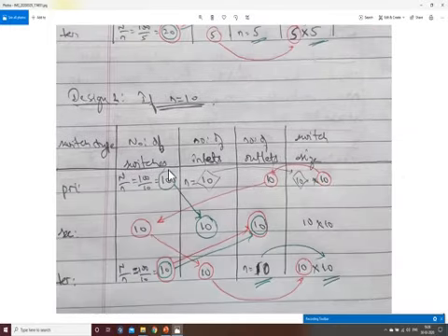So when we have N is equal to 10, we can observe that we again have 3 stages: primary, secondary and tertiary. The number of primary switches is given by capital N by small n, which is 100 by 10, which is 10 primary switches. Similarly, tertiary switches is N by n, which is 100 by 10, that is, there are 10 tertiary switches. Now this is another parameter.